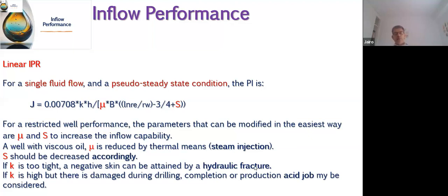Beyond that, you have a problem with the wells. Normally, people say we will do an acid stimulation. That is not acid stimulation. When the skin is positive, what you are trying to do is damage remediation. Damage remediation is not stimulation. So I hope this concept is clear. Damage during drilling, completion, or production, very carefully, as I explained.